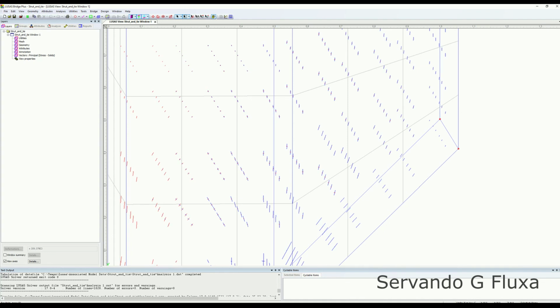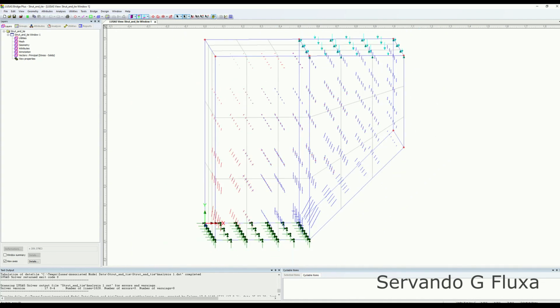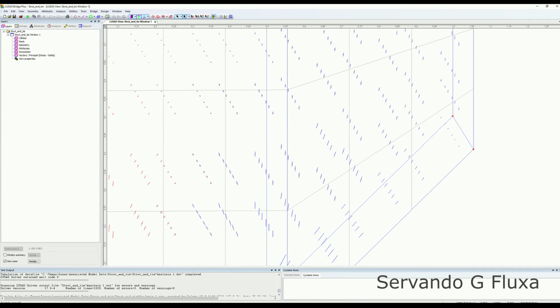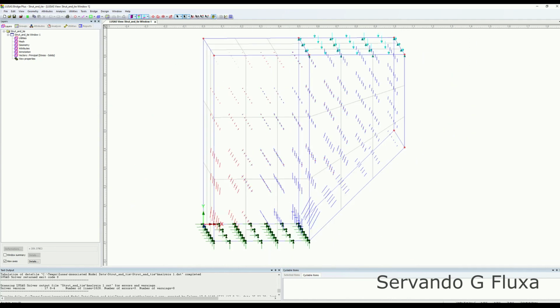That will be your links that are tying up. At the end, you're going to have reinforcement around here, going down. But you also need reinforcement in this direction, and what is telling you that are those little red lines that show there's tension going in that direction.